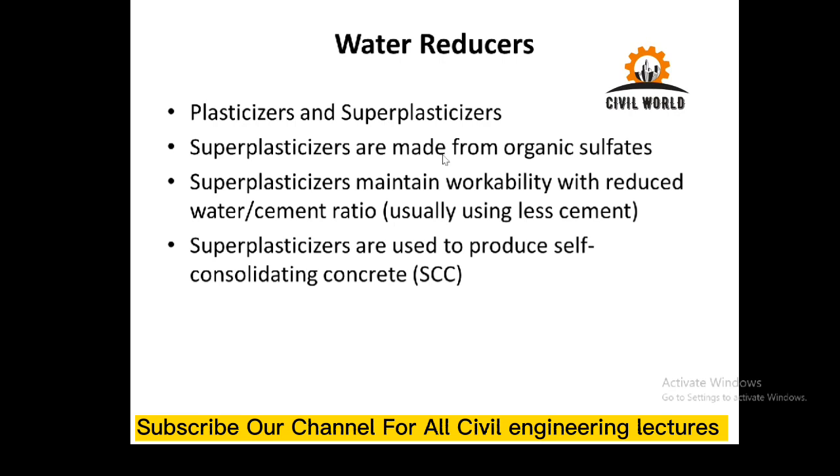Additionally, if compressive strength of concrete doesn't need to be increased, the quantity of cement may be reduced to achieve the same compressive strength with a lower water cement ratio. Additionally, using the same amount of water once the requirement of water is reduced, workability of the concrete may be increased.